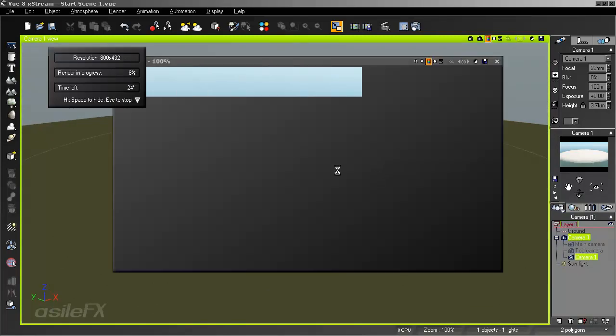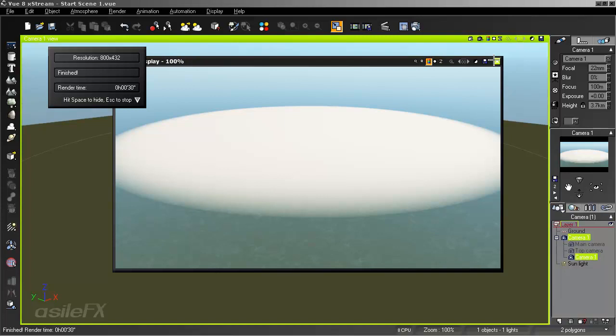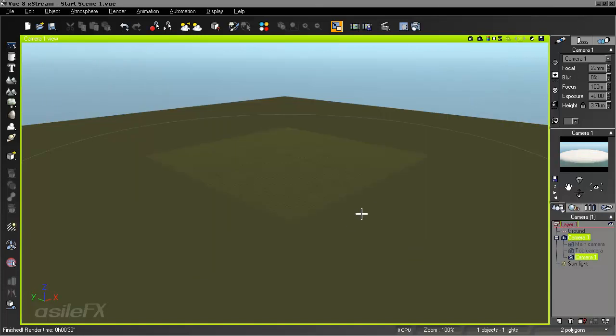and if you take a look at a render, what we're seeing is just the density created by the noise. Without the detail setting turned on, there is no detail subtraction, which is one of the primary ways or looks of the cloud layer. Really, depending on what you want to make, it's what creates all the fine little details, although it doesn't have to. It is possible to create an entire cloud layer with just these density settings.